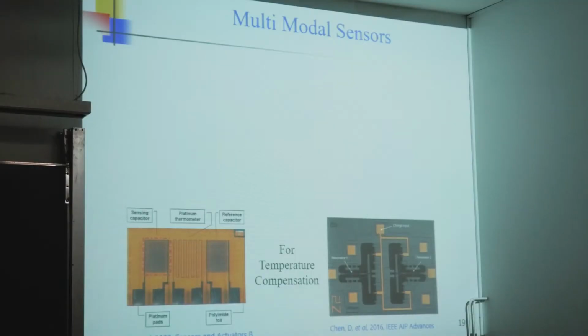All right, so let's add more function. We are dynamics people, so I guess we can do even better than this. One idea: let's look into multimodal excitation. In this sensing literature, what they are usually concerned with is the temperature influence on the mass. Essentially, if you have a clamped beam and the beam is heated, then of course it will get an axial force. It will translate into a shift in the frequency, which can be mistaken for a mass.